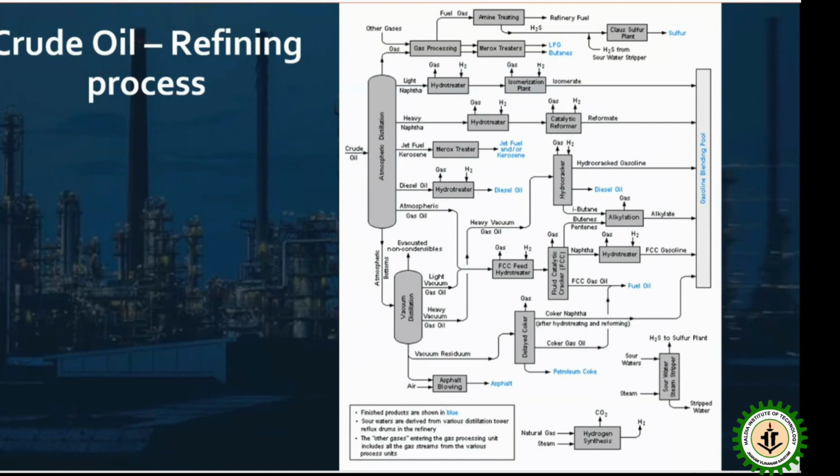Because in a refinery or petroleum, whatever things move, it moves from plus pressure to minus pressure. Means there is a pressure gradient. From the vacuum distillation, the vacuum residuum reaches the delayed coker. If you reduce the pressure further, if you get it further vacuum, there will be a problem. What will be the problem for a vacuum vessel? What could be a problem for creating a vacuum inside a vessel? Maybe break down the column also. Exactly, it will buckle up.